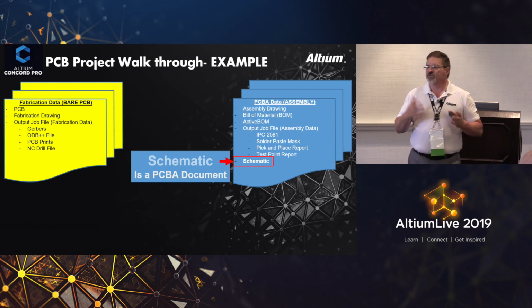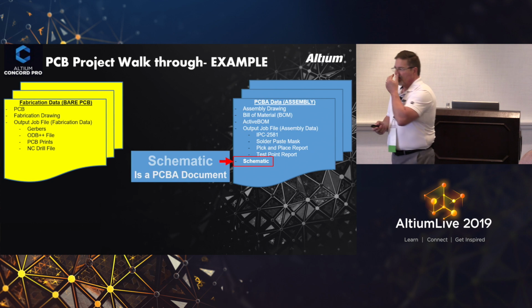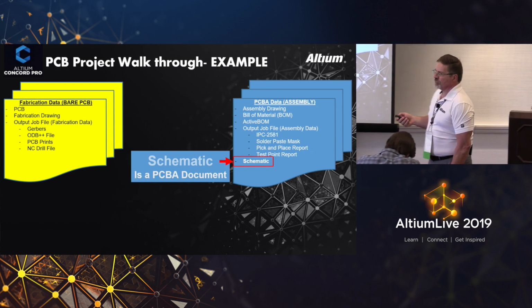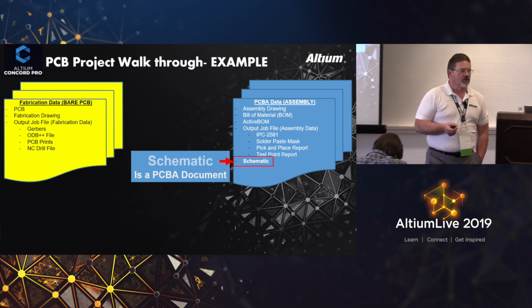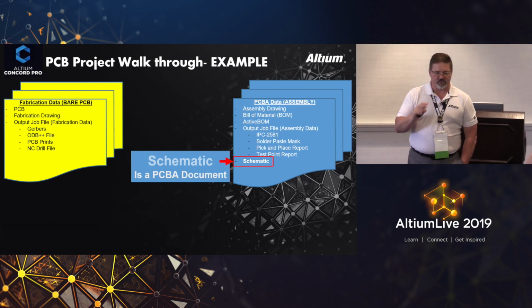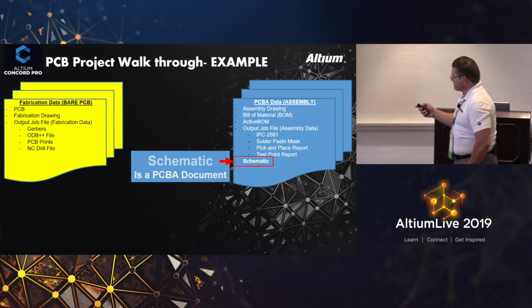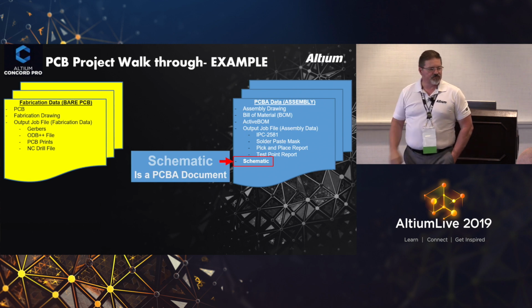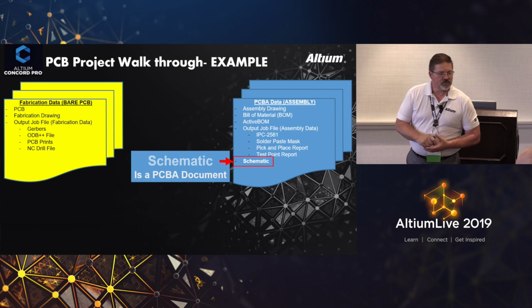Now, one thing that we do is we want to make sure that any of the revisioning levels that we use, we stay synced up in this way. Let me explain. Let's say we're up to 2A here, or 2C, and this is revision 1. It's never gone through any changes. PCB has never changed on us.